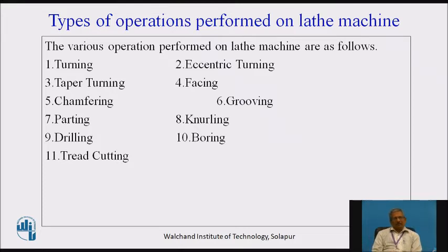material to be machined. If you observe in the market, certain tap wrenches, fixtures or holding devices are knurled for gripping or holding on the handles of those tools. Okay, drilling is the operation. In case of a lathe, as I told you, you can carry out drilling only at the center, or along the axis of the workpiece or along the axis of the lathe. So drilling can be carried out by using the tailstock.